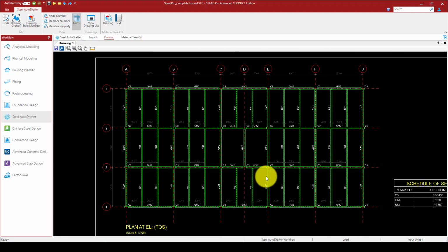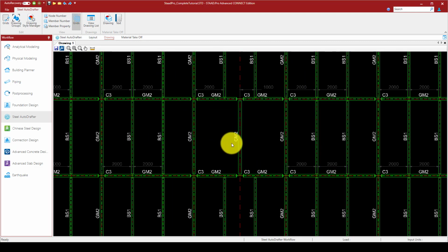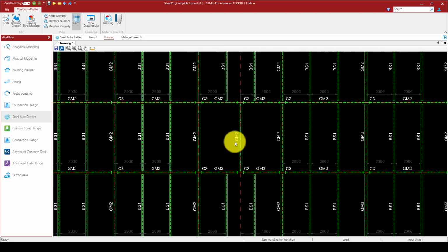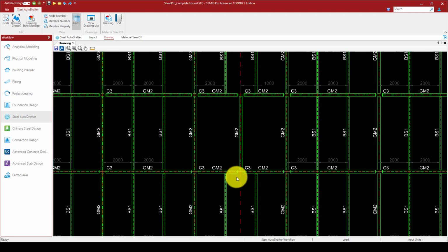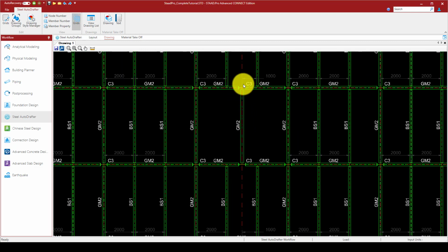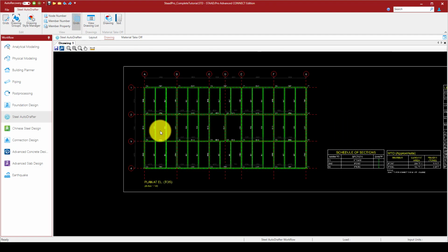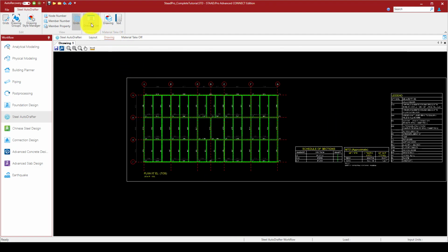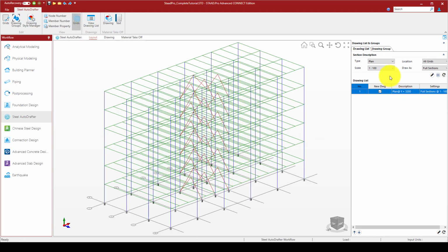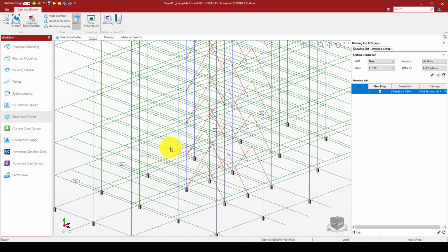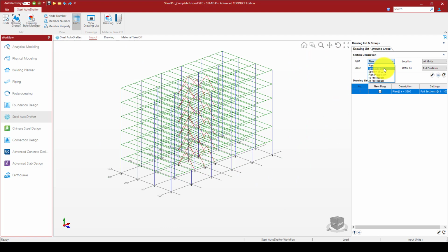So this is my first floor plan, and here the program automatically determines a single beam. We have one column, so it's a small beam here. Then we go back again to the view list, and this time I want to select the section. I'm going to call section across X, and across Z in this direction. You can reduce the scale and use the wedge length, so totally 15 meters.